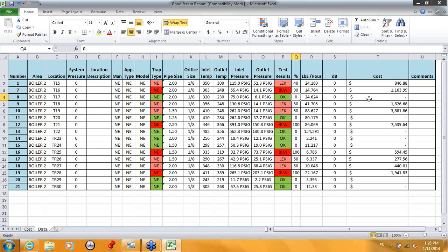And you can tell just by listening to it if it's chattering or if it's leaking through, blowing through, or if it's just okay. But you actually have to make contact, listen to that cycle, and see if it's actually okay or not. And then once you decide on that, you can plug it right into DMS saying it's leaking by, and it'll bring that information over to the spreadsheet. And then it'll start crunching the numbers for you and spit out a dollar value. Okay, so it's almost similar to the leak surveys that we have for the leak application, but this is just for steam.